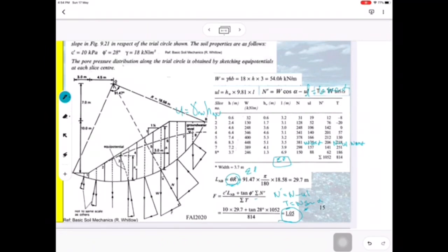Okay, so FOS is normally less than 3, or maybe just a little bit over, 3 point something. When you do exercises, if you get your FOS equal to 100 or 20 or 50, there must be something wrong with your calculation.